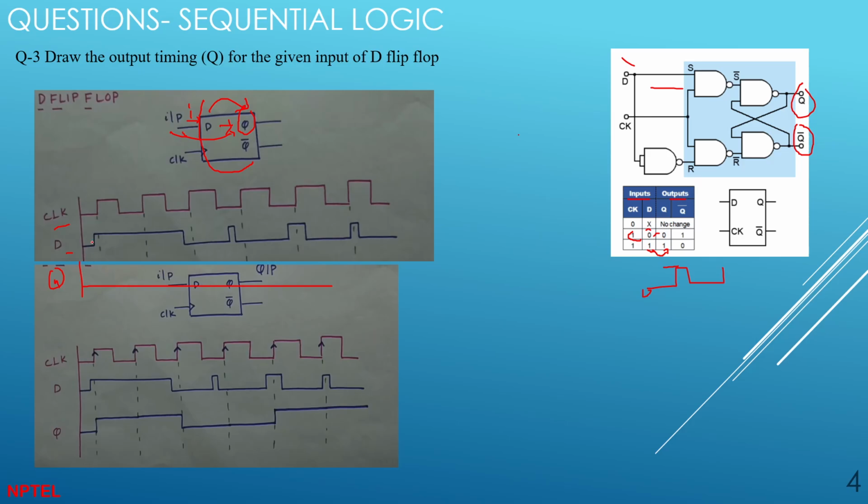Let's try to solve this kind of question. These are edge triggered, so please remember that whenever there is a 0 to 1 transition, only then does the clock trigger. You can see here I have drawn some edges, and D is the input. We need to find out what Q is, which is the output.